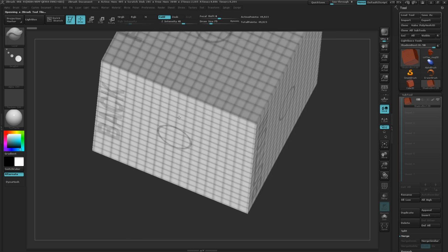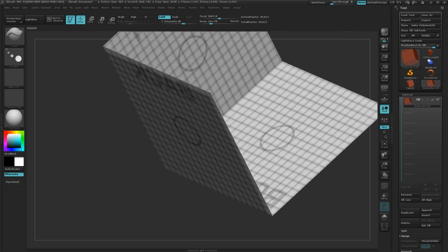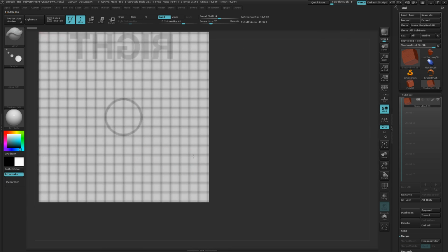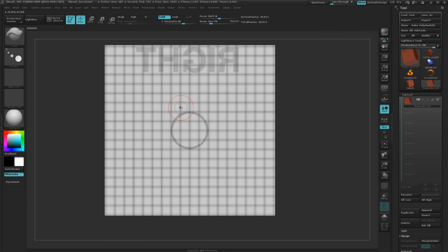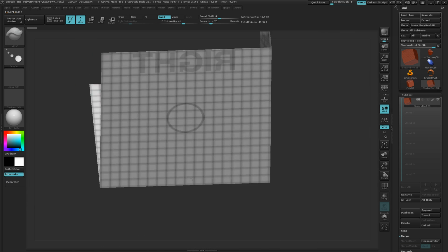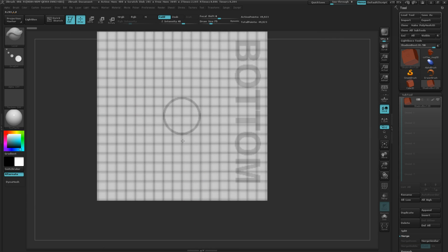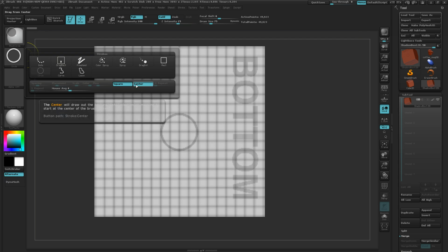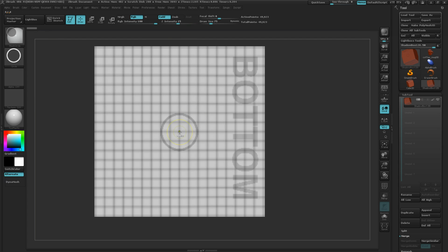You see it's got three sides: back, right, and bottom. So what I'm going to do is go to the right side over here and just hold out. Actually, probably best to go to the bottom first, and you can do it either top down or bottom up. It's got a nice little center dot in it, and I'm going to hold down my Control key and get my mask circle tool and make sure I've got square and center turned on for it, and just draw out a circle, roughly the size that I want to do the mug.